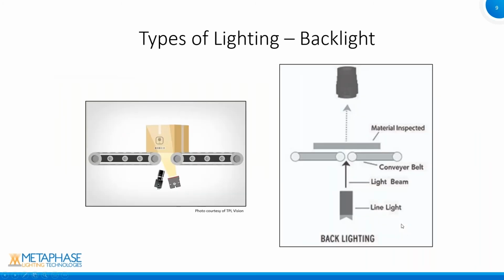As I mentioned, backlighting is another way that we can use line light illumination. And generally speaking, you may be familiar where you have a backlight shining in the same direction as a camera, but you can also, in some ways, be illuminating the part from beneath if it is transparent enough. This is really valuable for looking at holes in materials, especially large sheets of metal, or even something like coiled steel, which is like for roofing materials. And this gives a really precise accuracy on the size and placement when you're silhouetting.